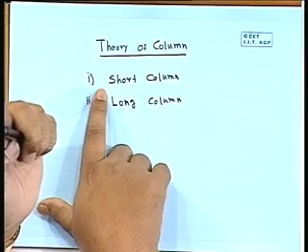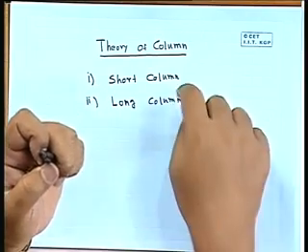Right. Say if we take this pen, it has a cross sectional area. So, if we take that length, the phenomenon will be something like that, and if we cut a single small piece from here, the cross sectional area is the same, but the length is rather small, or we could take a much longer stick having the same cross section. So, structural behavior of a small piece and a long piece will be entirely different. So, the ratio of the length compared to the lateral dimension will give the guideline whether the structural component can be handled as a short column or a long column.